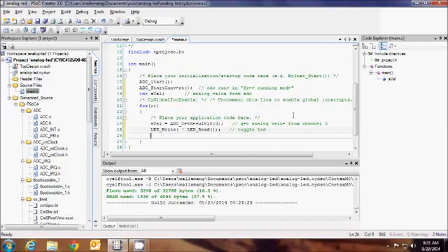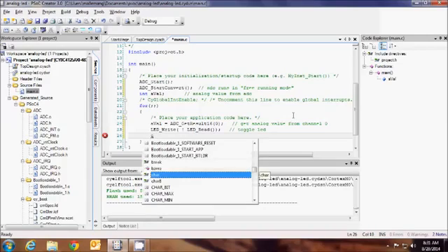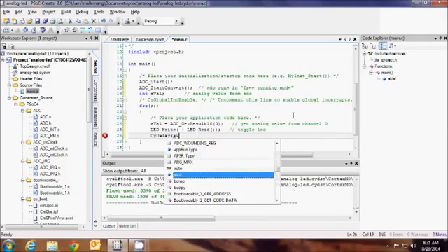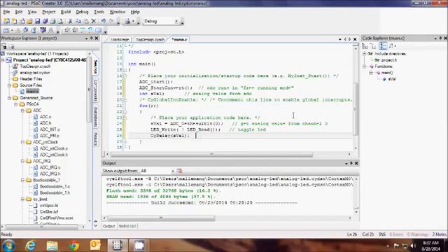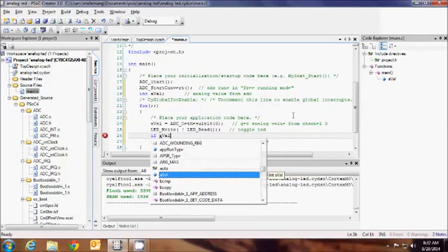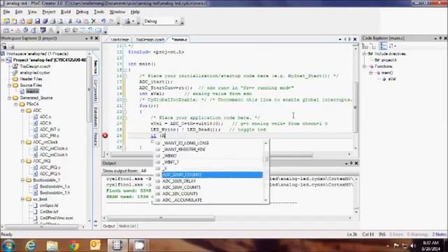And now we have to delay based on the analog value. So it's CY delay, and you specify milliseconds. So the analog value will be 1 to 2047 milliseconds. So that's roughly a 1 to a 2 second delay. Not a 1 second delay, 1 millisecond to 2 second delay. So yeah. Okay, here's where I'm going to limit check the analog value. Limit it to 1 to 2047.